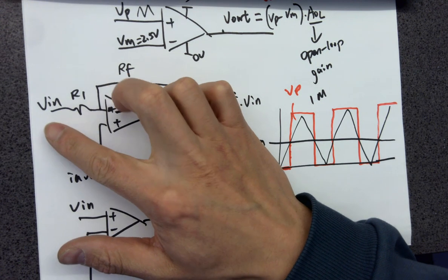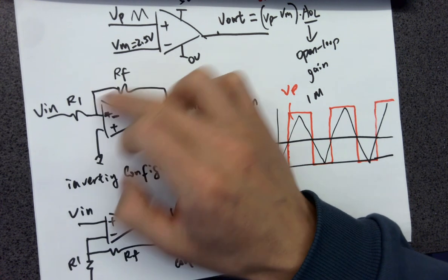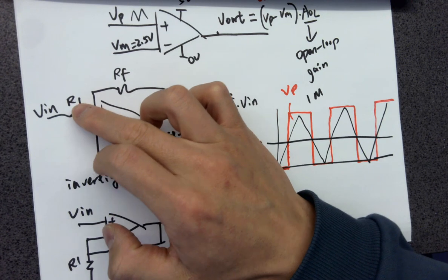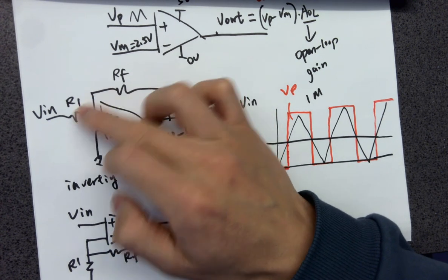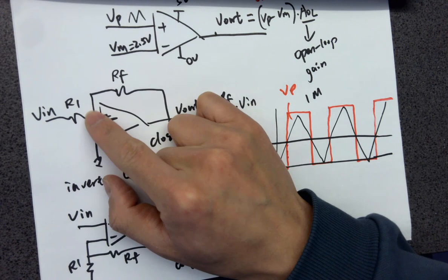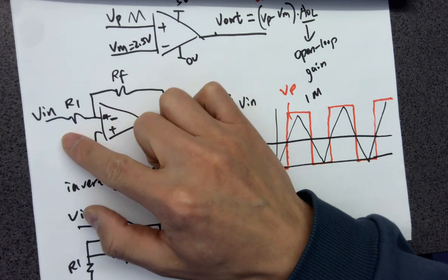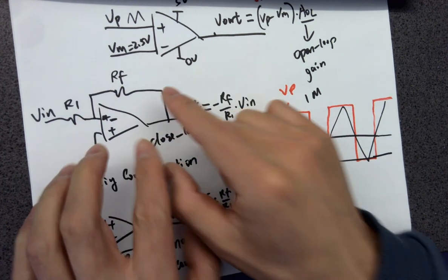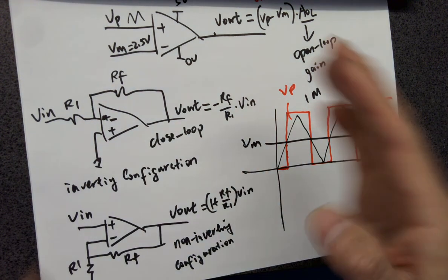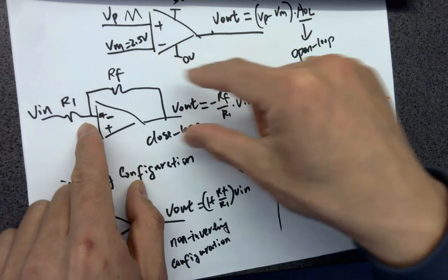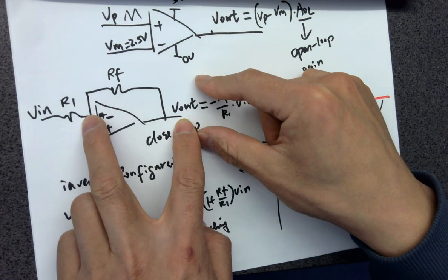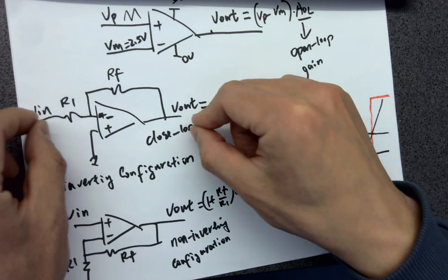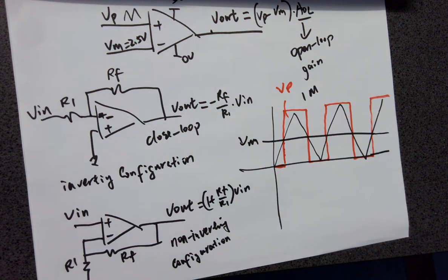You usually don't make the gain larger than about 20. It amplifies the DC mismatch a lot, so eventually it's going to saturate. If you need to amplify 100 times, you add multiple stages, like 10 and 10. 10 times 10 becomes 100, and you add filters in the middle. This is really important stuff to learn about.